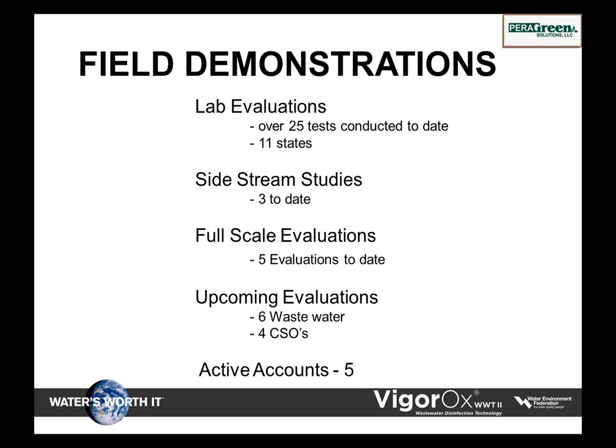I looked at the lab studies, and in every application I've gone to, either side stream or full scale, I'm exactly half the dosage of what I found in the lab. Reason for that is you're using a dilute solution of PAA for lab studies, versus feeding it neat. And that's one of the key points at the end.